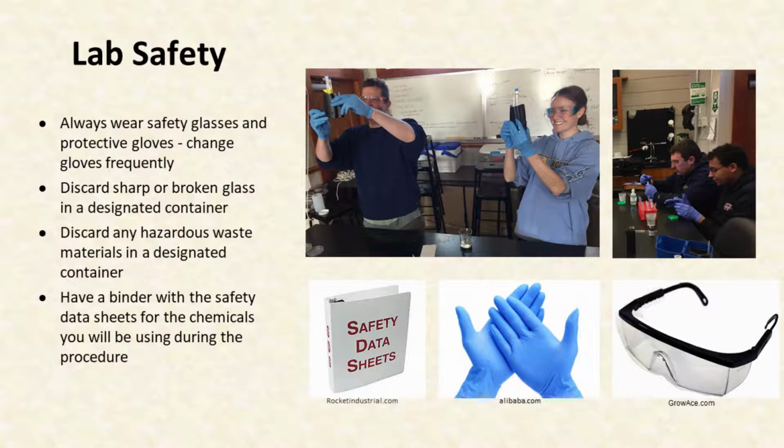Some samples may be taken back to a lab or office to be tested for additional parameters. While in the lab, always wear protective eyewear and gloves. Some of the tests require the use of chemicals and can pose a hazardous risk. Gloves should be changed frequently to avoid cross-contamination of samples and hazardous chemical exposure through unnoticed ripping or tearing of the latex. All potentially hazardous chemicals are equipped with a safety data sheet.